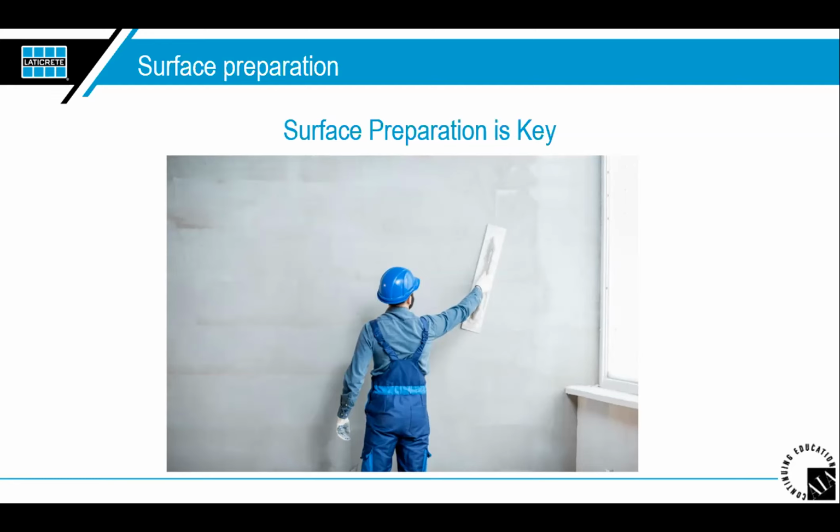Those kinds of things are easy to point out, because I don't know any manufacturers currently that make one-sided thin set. It's a little term that we like to use in the industry. If we have a great bond to the back of the tile, but not to the concrete substrate, there is some type of bond breaker happening there. If we have a great bond to the concrete, for example, and not to the tile, then we also know there was a bond breaker on the back of the tile too, which can show up in many different forms, such as a kiln release.